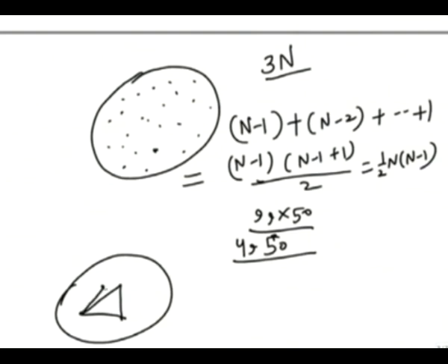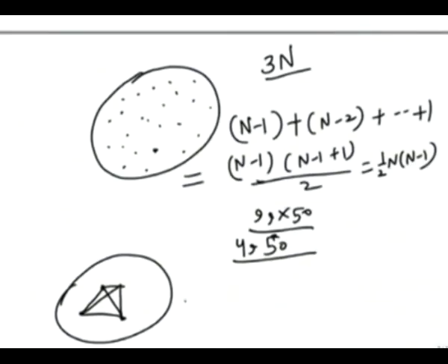So once you have fixed 3 points on the body, all other points get constrained. They cannot have independent degrees of freedom. So we can only take 3 reference points, but the 3 reference points themselves are also not independent, since there are 3 equations of distance. Thus the independent degrees of freedom are 3 into 3, 9 minus 3, that means 6. So there are only 6 independent degrees of freedom.